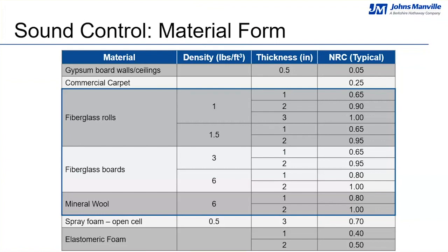Thin pile commercial carpets provide some sound absorption with an NRC of around 0.25. However, many facilities such as museums, hospitals, restaurants, or gymnasiums do not include carpet. They tend to utilize tile or even finished concrete. One thing we are seeing is that many open office plan spaces are moving away from carpeting as well. This further contributes to the overall noise level as hard surfaces like tile promote reverberation rather than inhibit it.